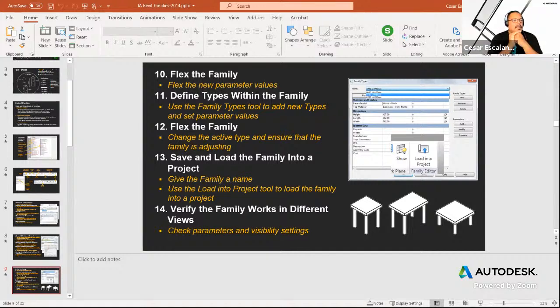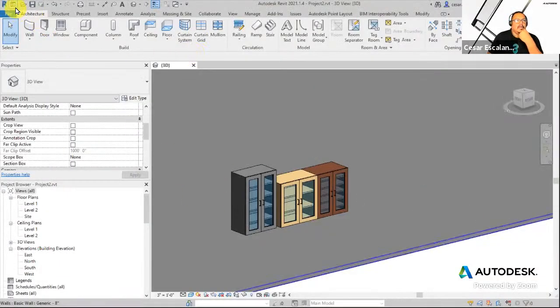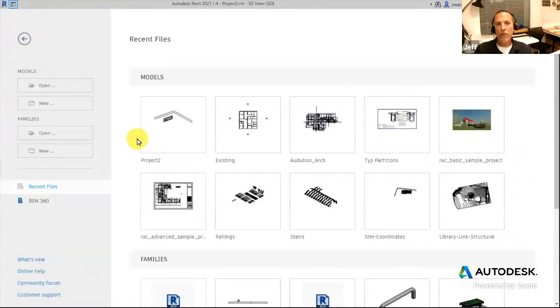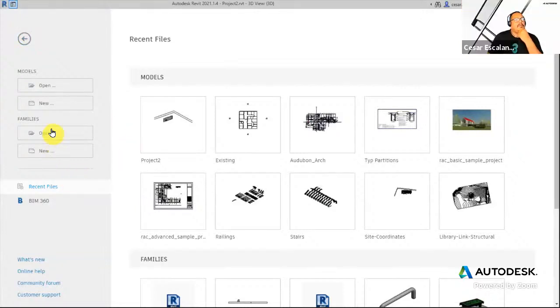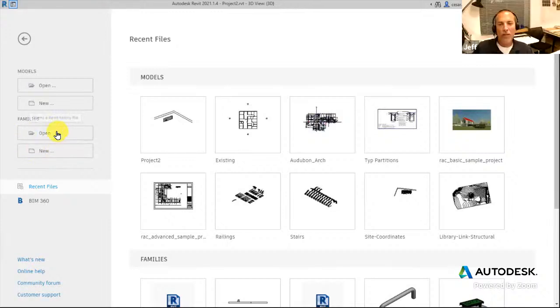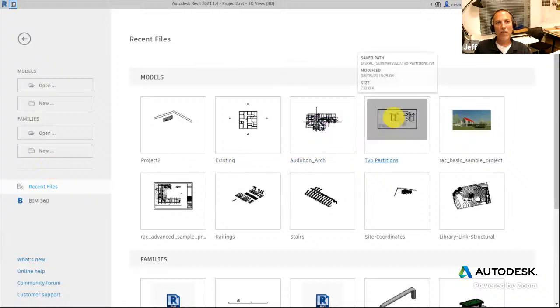No, Revit LT has the family editor. The only thing we can't do in LT is in-place families. We can edit families, actual RFAs, but we can't create an in-place family in a project. There is no in-place tool. You have to actually copy an in-place family from another project, put it into yours, change its work plane and stuff, and then manipulate it from there. That's the only way LT will let you do an in-place family, if you copy it from another project.